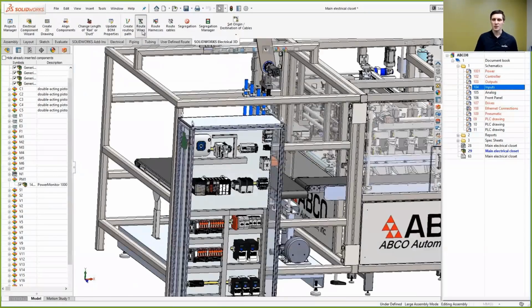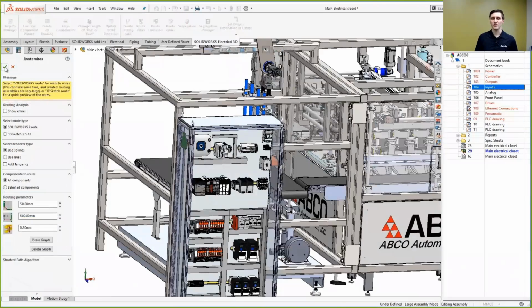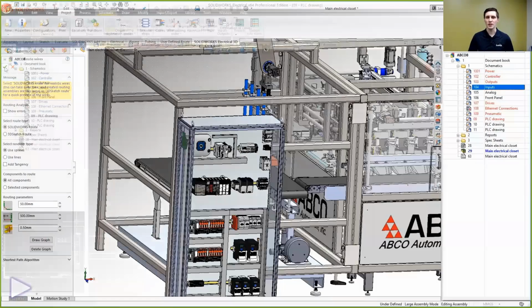The wires can also be automatically routed, and they're going to inherit bend radius and colors and core diameters from our project settings. So again, it's going to keep phase and control wires separated using special tools. We can get all of our cable lengths, and our duct fill ratios are going to be calculated to make sure we're meeting code. So it makes everything really simple.